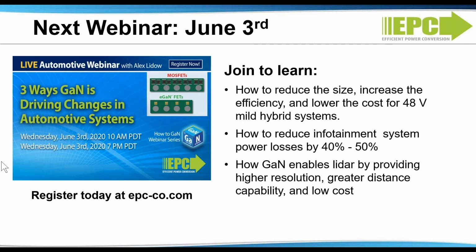For the 48-volt input converters, does EPC recommend 80-volt or 100-volt FETs? I think that we don't have a lot of 80-volt FETs, so we're applying 100-volt FETs to it, and as you can see, they're much better than MOSFETs. But I don't think you need anything more than 80 volts on that.